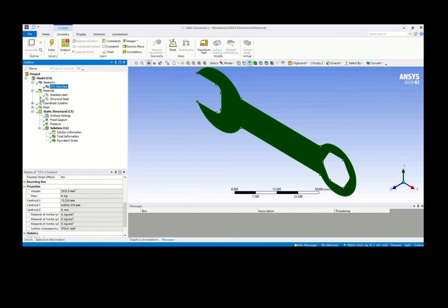Then next will be the mesh, because this is just one component itself, so it doesn't involve any connections. Later on in the 3-dimensional model, we have 3 components coming in. Then there are connections that you have to really look into, whether they are connected correctly. The contact is correctly assigned. So next is meshing.